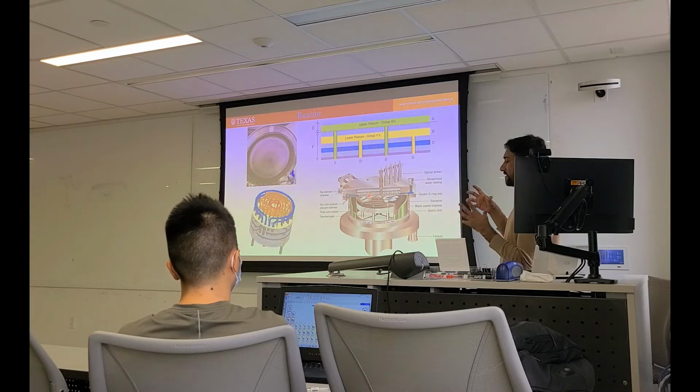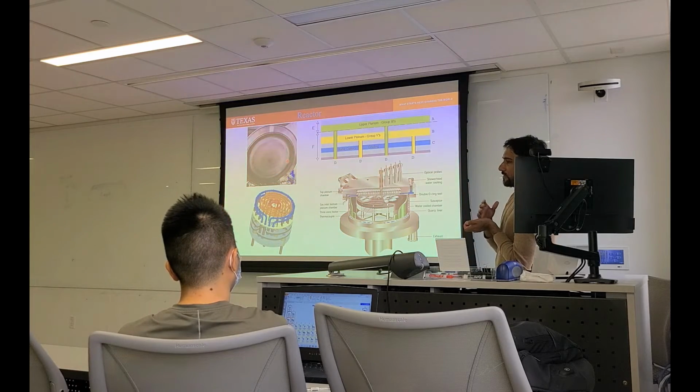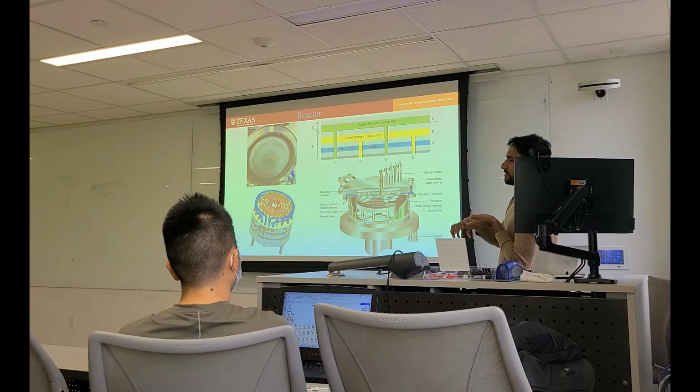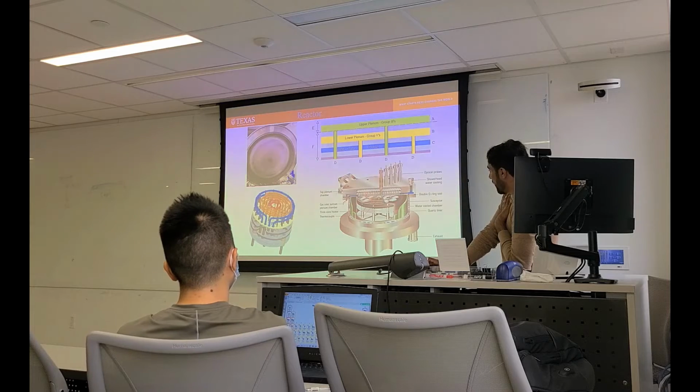They don't mix inside the shower head. You cannot mix your group 5 and group 3 precursors inside the shower head. They will be mixed when they flow outside. Then you are also flowing the vertical carrier gas just to speed up the flow to the substrate side. When your substrate is heated at different temperatures, then reaction can happen. I will tell you how the reaction happens in the coming slides. This is only about the shower head.